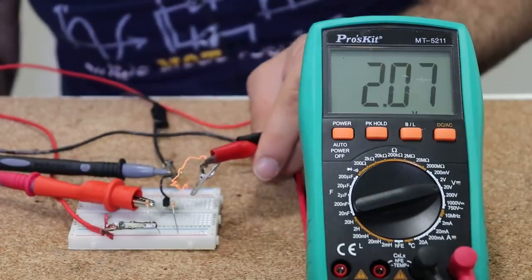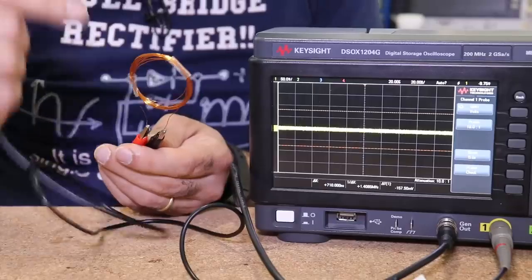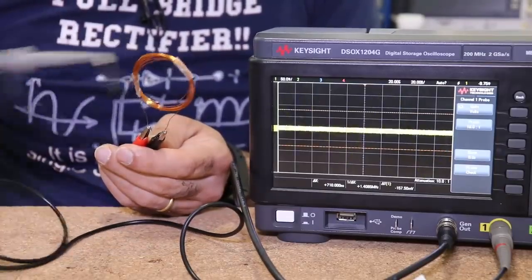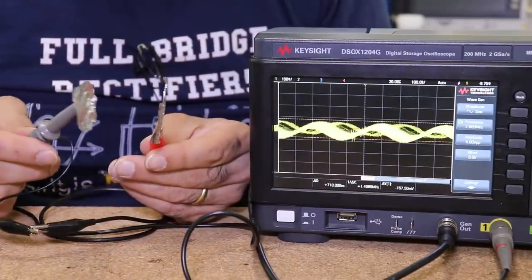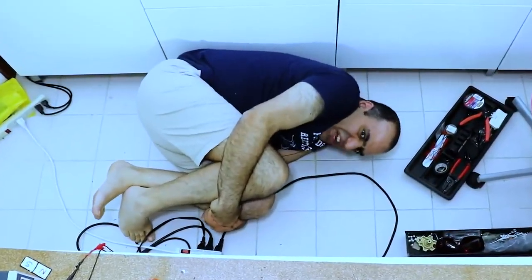This makes life very easy, because if components don't bottle up their stuff and radiate around, they start affecting the surrounding circuits, and this crosstalk between the components makes it very hard to analyze circuit behavior. For example, if a hot resistor gets close and warms up a transistor, the transistor parameters are significantly affected. If an inductor radiates magnetic fields, it will induce unwanted current in the neighboring circuit loops. If electric fields leak from a capacitor, they can create unwanted voltage on neighboring conductors. And all these leakages make it very hard to understand the circuit behavior. Everything is lumped. No one is affecting anyone else.